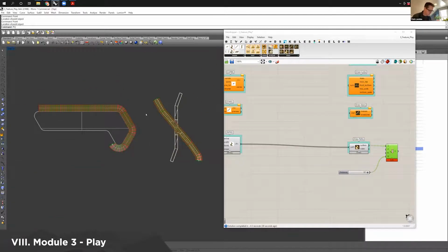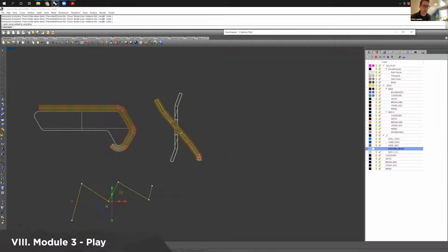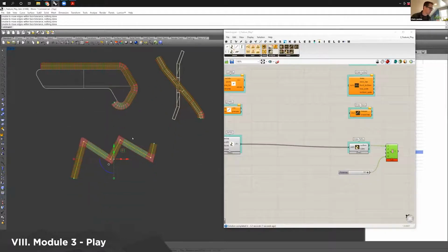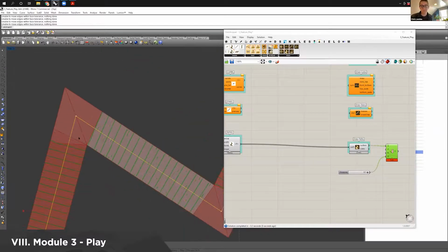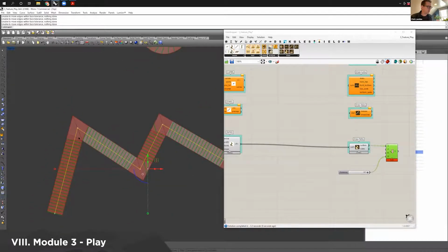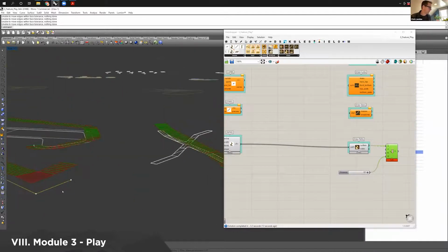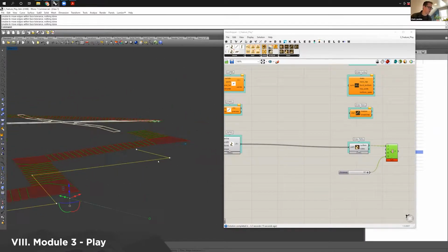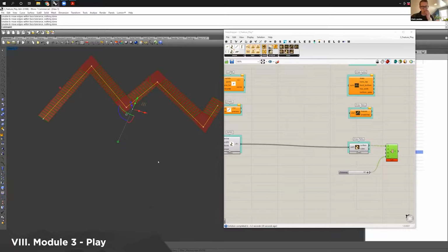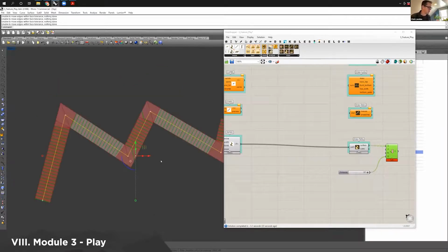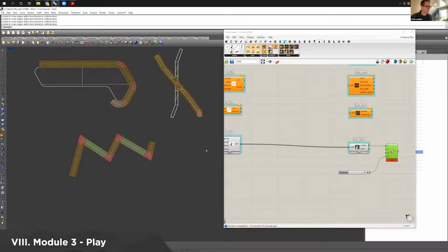And also, just so you know, if I have a center line, just change that to here. And of course it has to recut those contours. If it is a polyline that doesn't have those beautiful fillet curves, it will create a flat landing at the edges, so that you don't end up with really wacky grading at those edges. It's pretty dynamic. We worked pretty hard on getting that to work smoothly. So anyway, that's how they work.